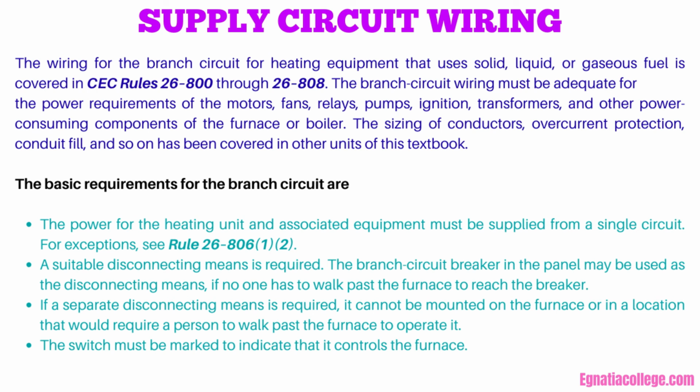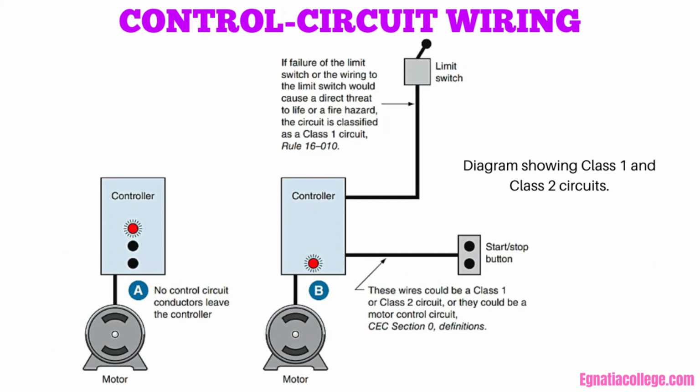If a separate disconnecting means is required, it cannot be mounted on the furnace or in a location that would require a person to walk past the furnace to operate it. The switch must be marked to indicate that it controls the furnace. Control circuit wiring.